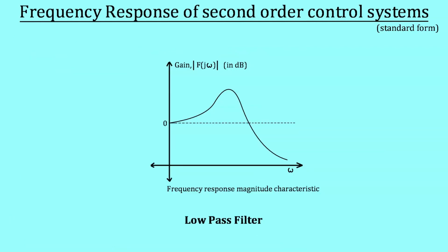Observing carefully the magnitude characteristic graph, you will realize that the amplitude provided by the transfer function decreases significantly after a certain value. In other words, we can also say that the system allows only certain frequencies, and after a certain point, the transfer function begins to attenuate the incoming signal significantly. And that's why the shown characteristic graph is actually a graph of a low pass filter.